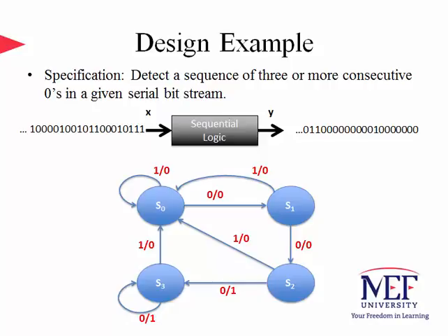After giving you a brief insight about why runs of zeros and ones might be important, let us proceed with the corresponding state diagram. Our system begins with the reset state as S0, where we assume the input bits start streaming. As long as the incoming bits are 1, we stay at the same state until a 0 bit carries us to the next state, S1. If the next bit after 0 is 1, we go back to the initial state S0. If, however, we have another 0 and another 0 after that, we will end up in state S3, where we give an output of 1, meaning that we found 3 consecutive zeros.